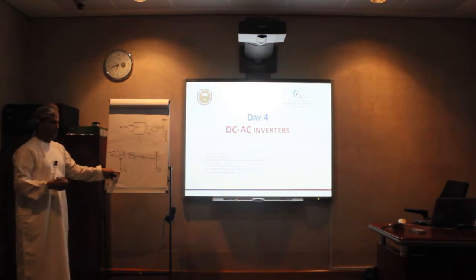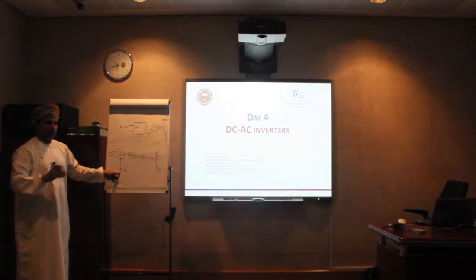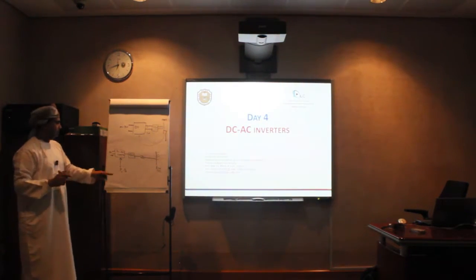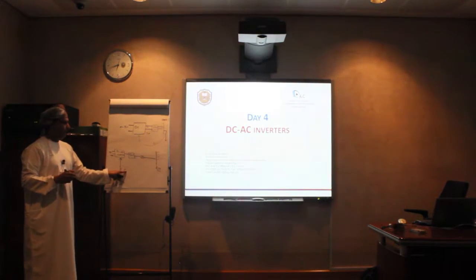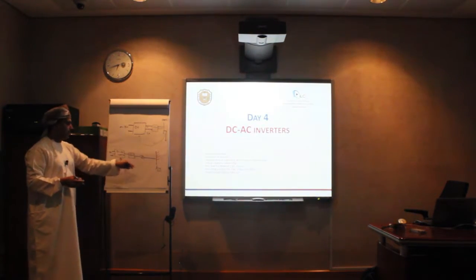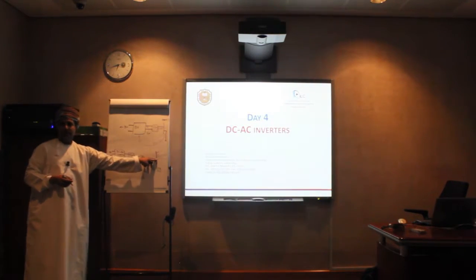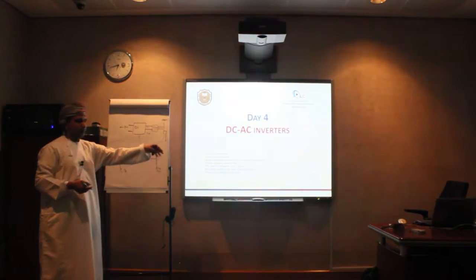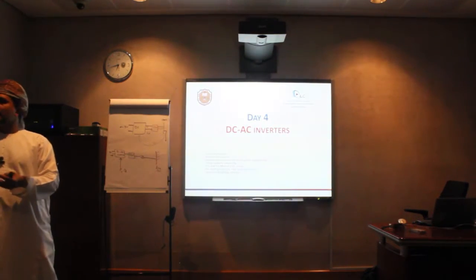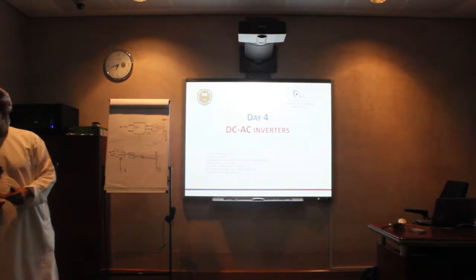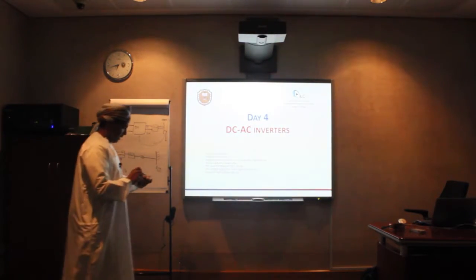No, mostly until now they just use it to control the real power, and they operate around unity power factor. It could be 0.95 lead lag, but reactive power, until now, is rarely injected from renewable energy sources. So this is the difference between those. Here I need to control those because this voltage and frequency are decided by the grid itself. However, in standalone, for example, if you need to make a system for your home, you need to control the frequency and the voltage, which is a standalone or isolated system. Is it clear?